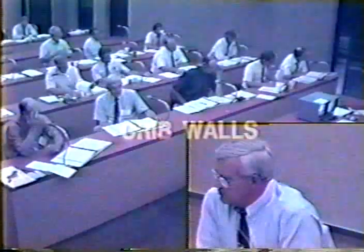Let's talk briefly about some other... Before we go on, one comment about that blanket of stone that you showed, particularly for the mud flow type slides. If we're going to be constructing blankets that are 2 to 3 feet thick coming down the slope in mud flows, they need to be keyed in at the toe. Most of them cannot support their own weight. So you're going to have probably whatever the width is of the blanket, the thickness of the blanket, at least that much embedded below the ditch line itself. That's a good point.